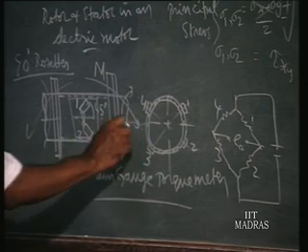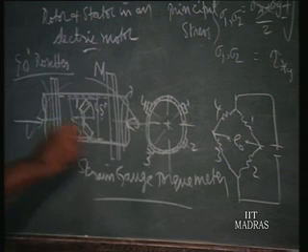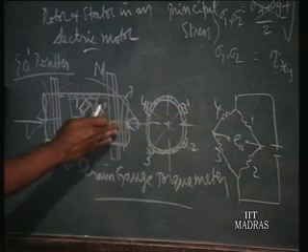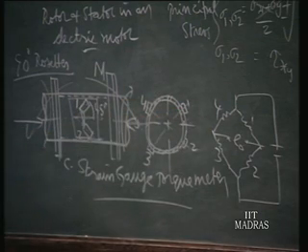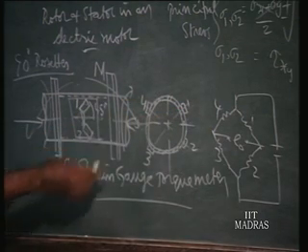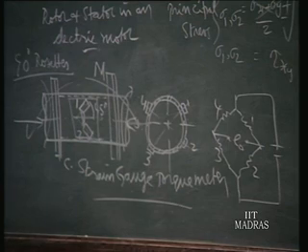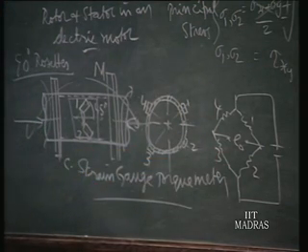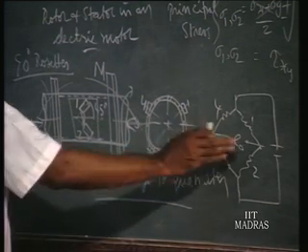Similarly, suppose you apply a compressive load and the whole shaft is compressed; will you get any error signal? No. It is because when you compress the shaft like this, all 4 strain gauges are equally strained, and equal strain in all 4 arms, as you already learned, will not give rise to any signal in the bridge network. So this is the law of the bridge.